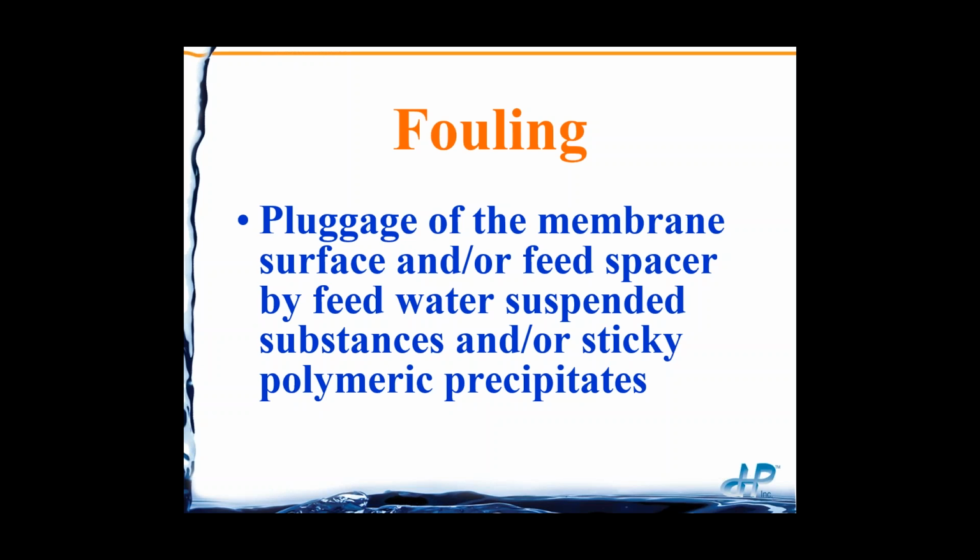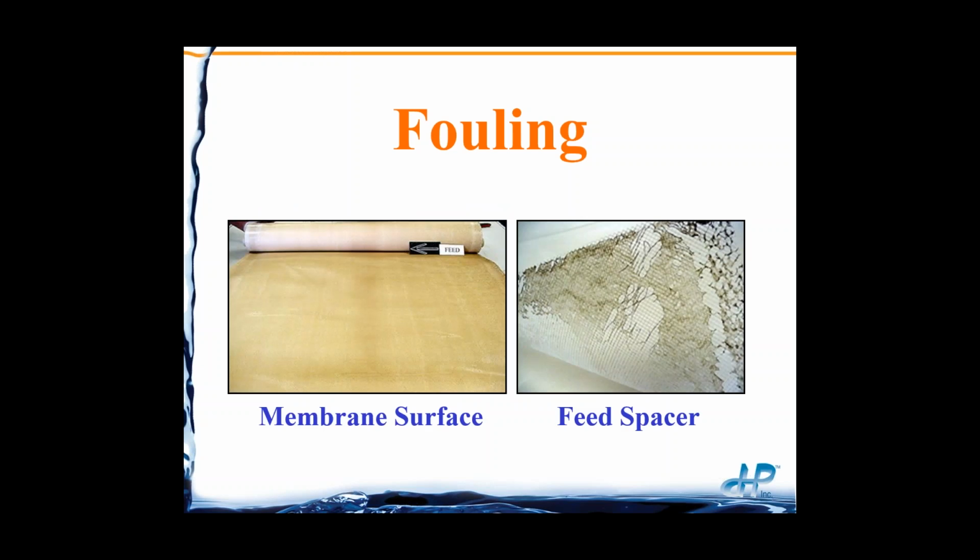or we also consider fouling organic polymeric types of materials, oils, greases, polymers, anything that can come in and doesn't leave. So it sticks to the membrane, sticks to feed water spacer. So we call that fouling. So on the left, there's a picture of fouling on the surface of the membrane. And in this case, the feed spacer has been removed. And here is fouling showing that it's plugging up the feed spacer. So the feed spacer would be laying on top of the membrane.